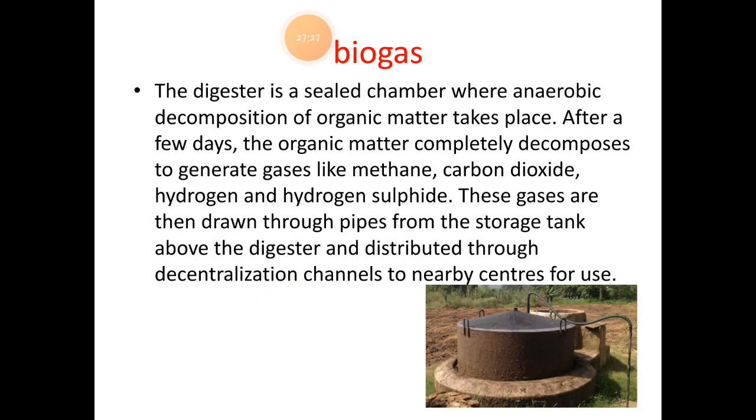After the waste is added, the inlet chamber is closed and it is left for a few weeks, and the digester's central chamber now shows anaerobic decomposition, which will release gases like methane, carbon dioxide, hydrogen sulfide, etc. These gases are harvested and distributed through decentralized channels for household purposes.